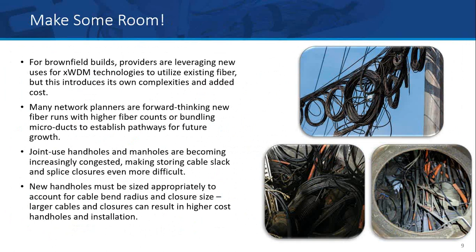So in brownfield builds, you're seeing some adjacent technology being used to try to leverage what's already in the ground, what's already in the air. So XWDM technologies, we're seeing that quite a bit as the service providers are starting to deploy 5G. We're starting to see what they call coexistence elements and things like that, to basically put more bandwidth over top of the same fiber that's already there.